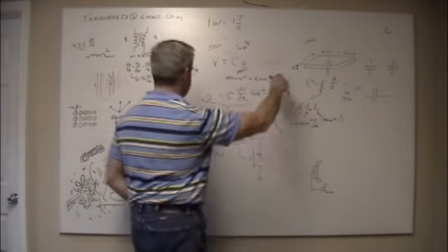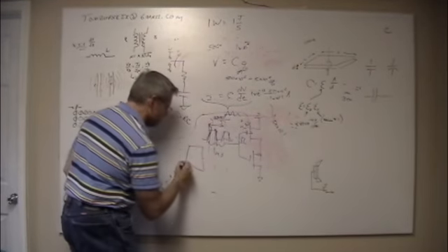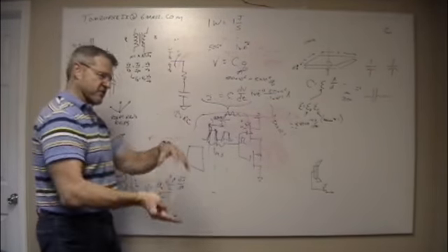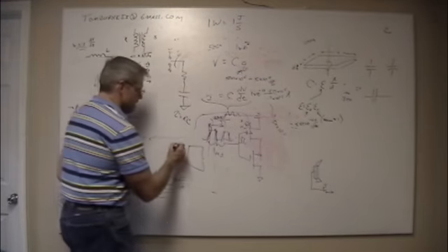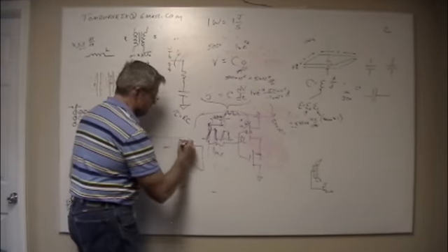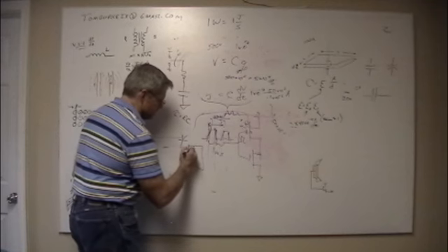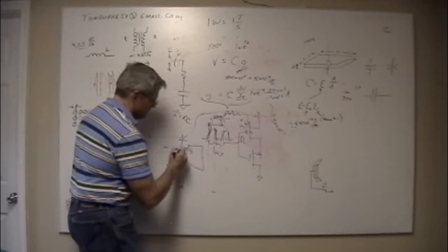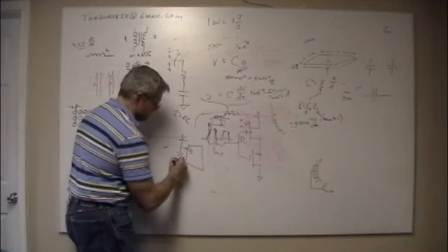So what I do is I come in really close to this chip that's got all these millions of transistors turning on and off and turning on and off, and here on the voltage line going in, V, and here's my ground. I put a big honking capacitor right there.